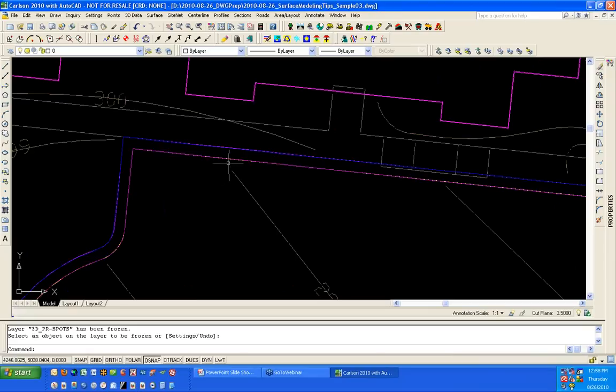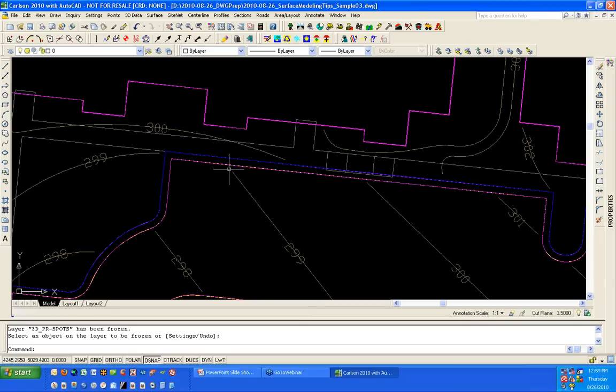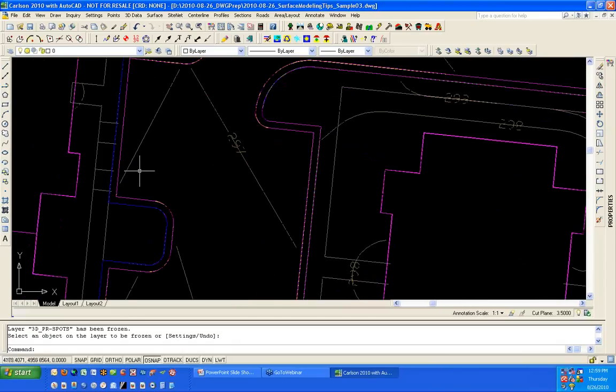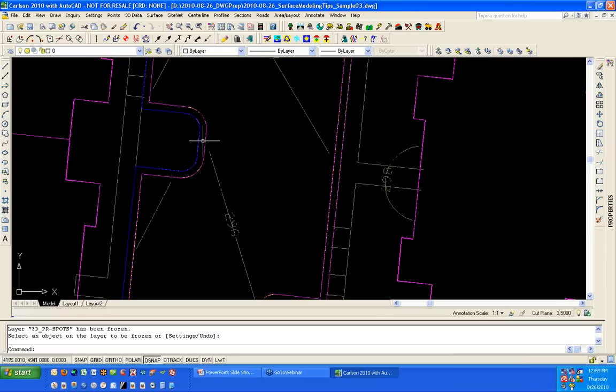After you do that, go back in and trim out where those contours would have crossed and create a conflict. Because, again, we don't want to create that bit of vertical face. So I go in, and you can see I've just kind of trimmed it out. Now it's still going to elevate. It's going to triangulate properly. But what we've done is kept it from having two different elevations in the same XY point.